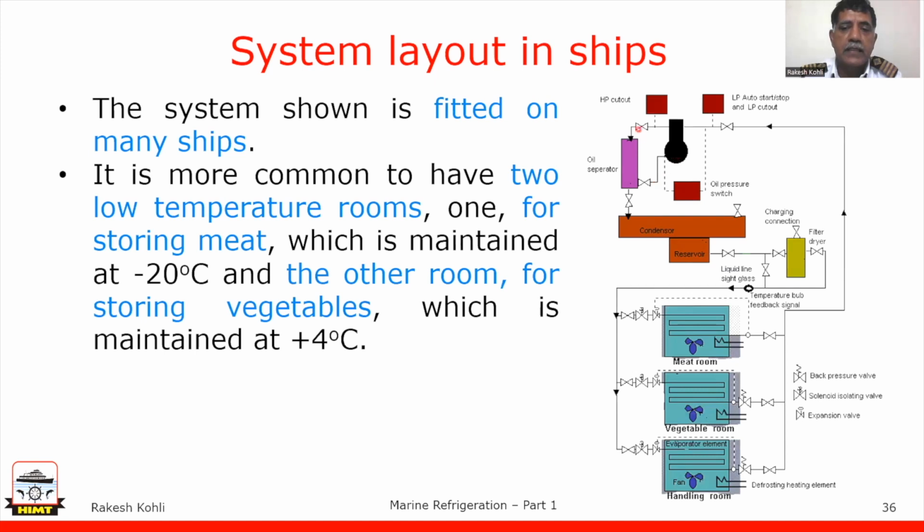So now let us see the oil separator. It's a cyclone separator where the oil is centrifuged outside, thrown out and collected at the bottom. A float mechanism will ensure that oil goes back into the sump at regular intervals once the oil level increases. The gas is passed through and it is cooled by seawater.